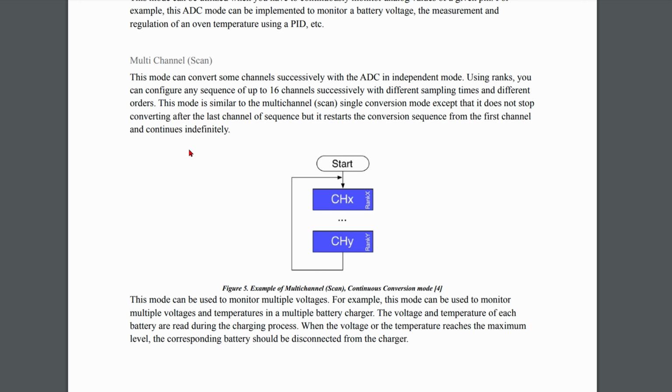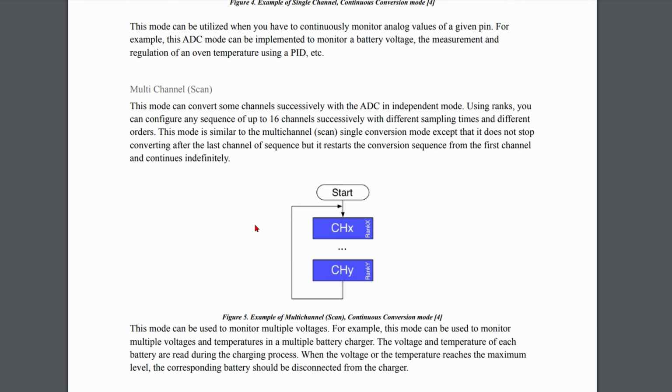So again, the mode is similar to multi-channel scan. It's a single conversion mode, except it does not stop converting after our last channel in the sequence, and it's just going to restart from the first channel, and it's going to continue indefinitely. Like what I said about the continuous looping here, we're just going to keep going.